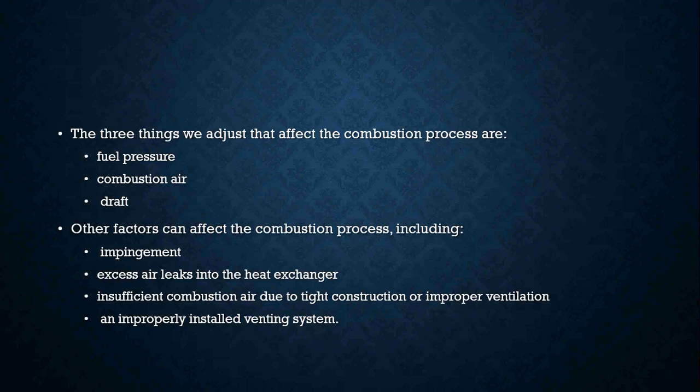Other factors that affect the combustion process are obviously flame impingement, which is something we do not want because flame impingement can cause carbon monoxide. Okay, excess air leakage into the heat exchanger. Okay, we want to make sure that we do not have insufficient air due to tight construction or improper ventilation. So we want to make sure that we have enough air for that unit to run correctly, and if not, we are going to have to make provisions to make it so.